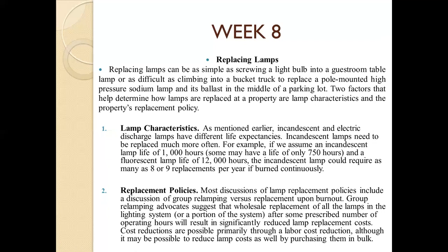For replacement policies, most discussions of lamp replacement policies include a discussion of group relamping versus replacement upon burnout. Group relamping advocates suggest that wholesale replacement of all the lamps in the lighting system after some prescribed number of operating hours will result in significantly reduced lamp replacement costs. Cost reductions are possible primarily through a labor cost reduction, although it may be possible to reduce lamp costs as well by purchasing them in bulk.